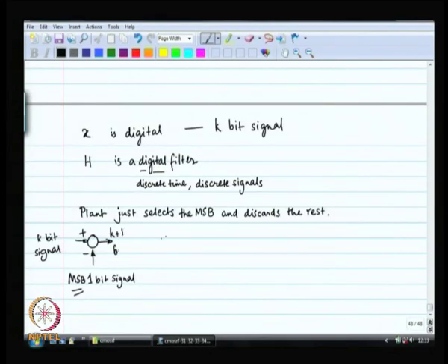Anything else that you have to worry about? How many bits are there here? K plus 1 bits, just in case there is some overflow, there is some problem. Okay. Because the MSB, there is one, both have MSBs, right. So, that is why just to keep some space, you keep k plus 1 bits over there.